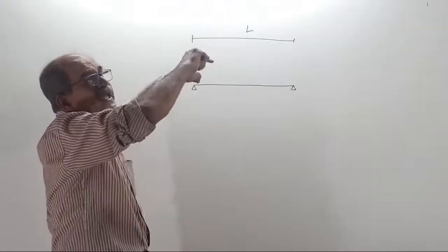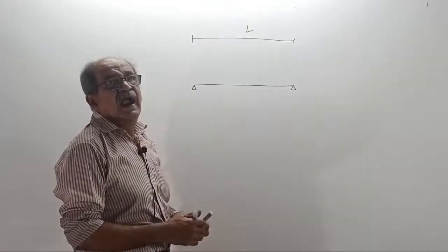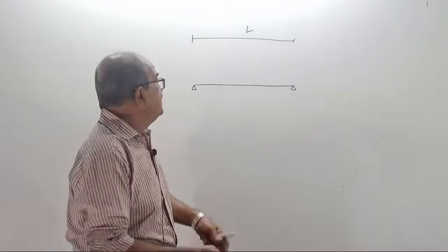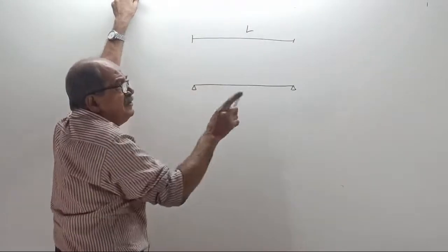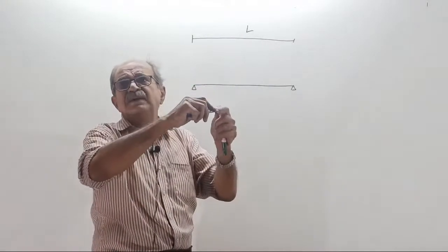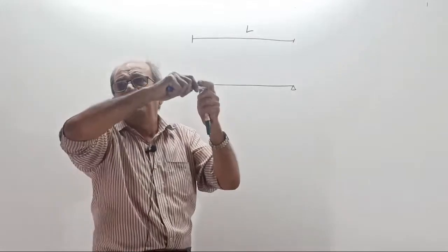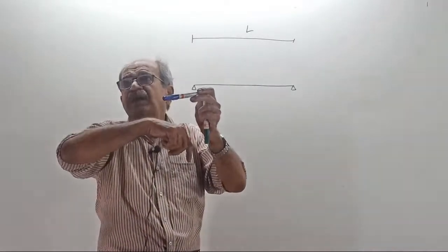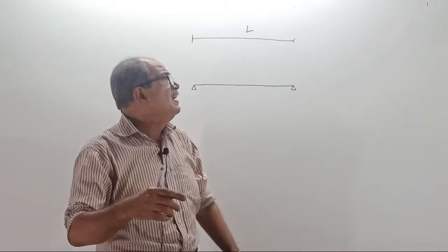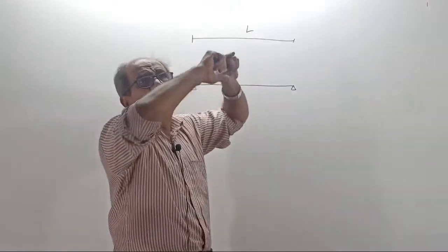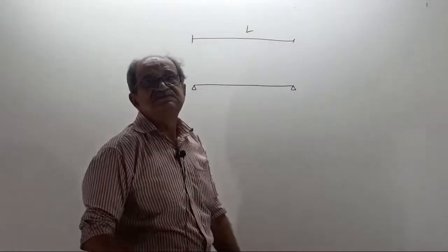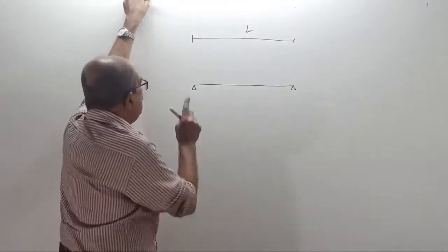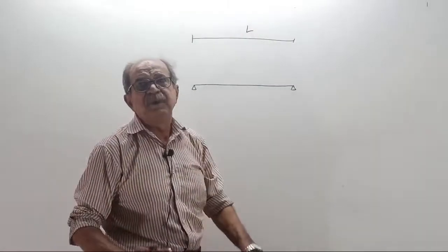For example, in a building, a floor beam is there. At the ends, columns are there. But actually, if columns are there, it becomes a rigid joint, and some reacting moment will be there. Just ignore it. Simply support it. The column is already cast, and you are placing the beam with reinforcement embedded inside the concrete. Or you can say a timber beam or steel beam supported by walls, so that we do not want beam and column to be monolithic. We want simple support. Basic is always simple support.